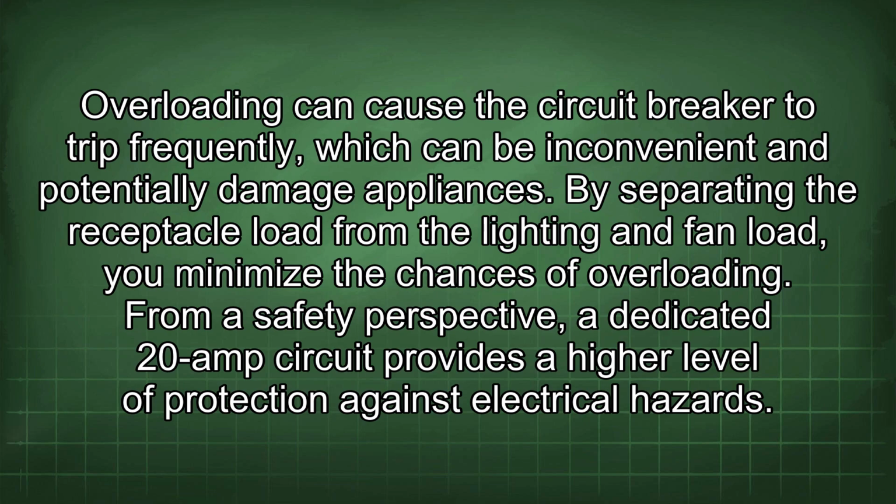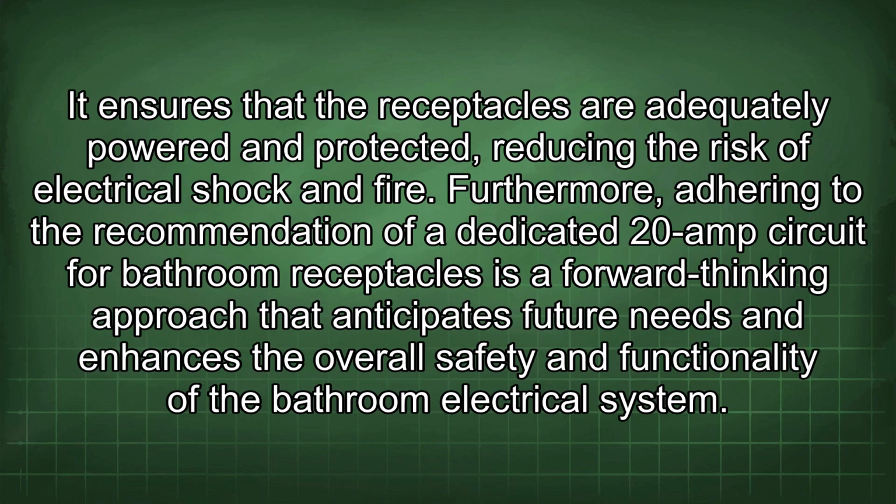From a safety perspective, a dedicated 20 amp circuit provides a higher level of protection against electrical hazards. It ensures that the receptacles are adequately powered and protected, reducing the risk of electrical shock and fire. Furthermore, adhering to the recommendation of a dedicated 20 amp circuit for bathroom receptacles is a forward-thinking approach that anticipates future needs and enhances the overall safety and functionality of the bathroom electrical system.